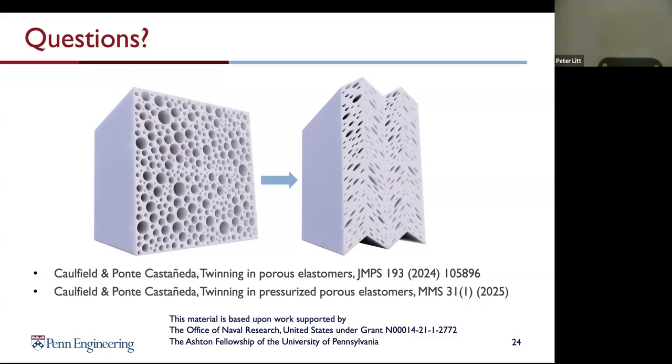The fact that this material is perfectly soft in shear in this domain means that if you try to propagate a shear wave through this material, it wouldn't get anywhere, because there's no shear modulus to drive that wave to propagate through. That is the case as long as the amplitude of your shear wave is sufficiently small that you never leave the twin regime. Because as we saw, once you get out of that regime, you again have a finite modulus. So if you send a big enough amplitude, it could maybe propagate a little bit, but if it's small enough that you stay in there, it wouldn't.